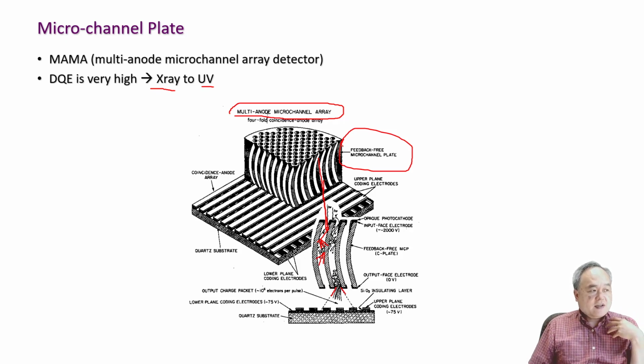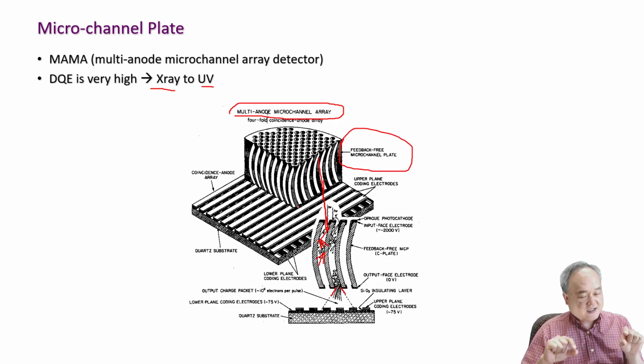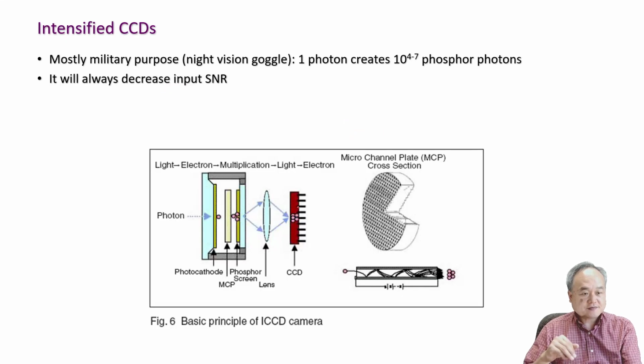The types of material you can use to create this microchannel give you far more freedom than selecting the right combination of photosensitive layer. In fact, a photosensitive layer suitable for high energy is pretty much non-existent. Remember that X-rays can penetrate a good amount of material, so thin photosensitive layers can be basically transparent to higher-energy photons.